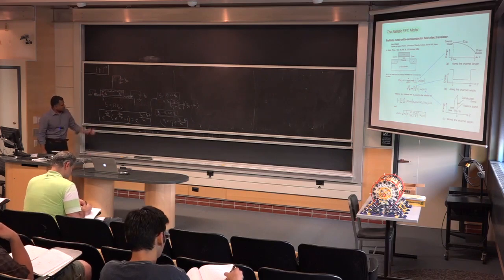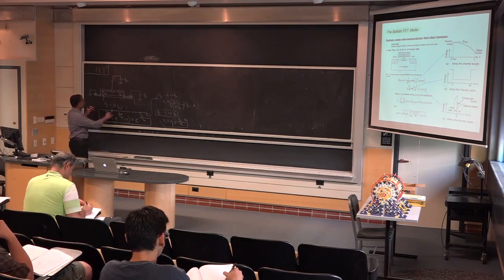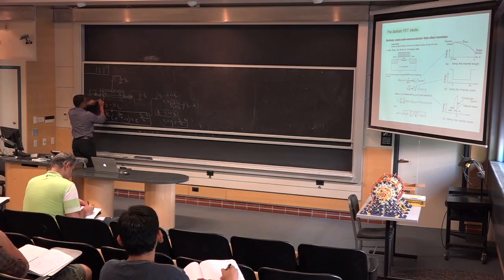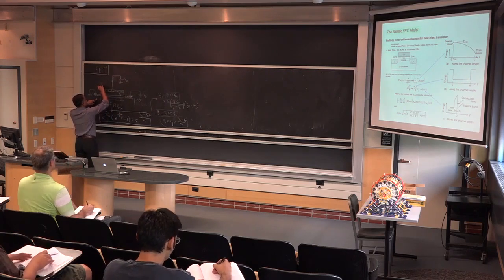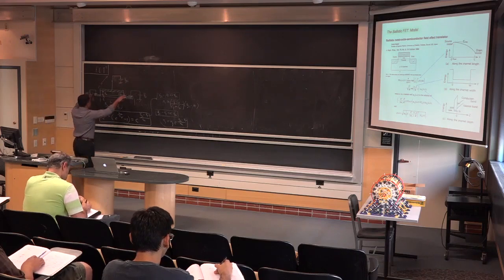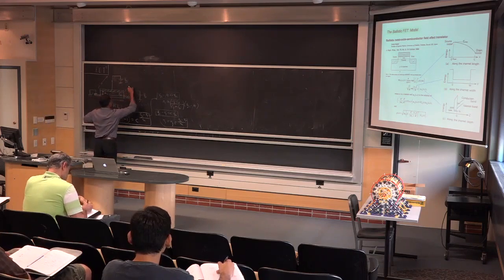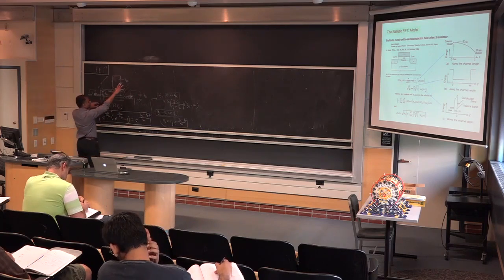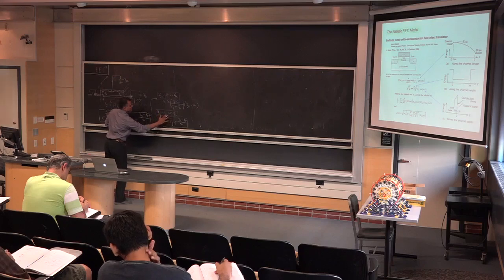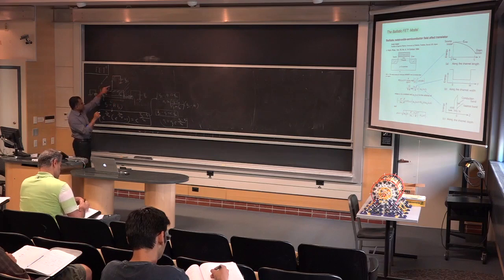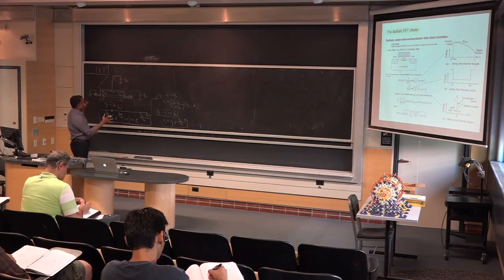So to set up the transistor problem, on the other hand, what we did was we imagined that the transistor has a length from the source edge to the drain edge. The length is L, the width is W. And we said that there are electrons that are going to be injected into the channel. For example, if your gate voltage was very low, there were not many electrons in the channel. And when you increase the gate voltage, you are filling electrons in the channel.